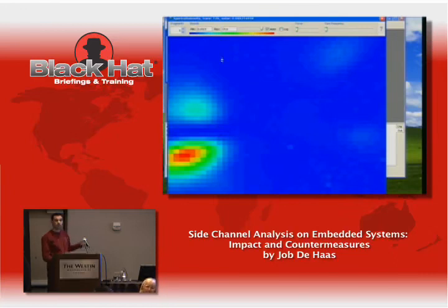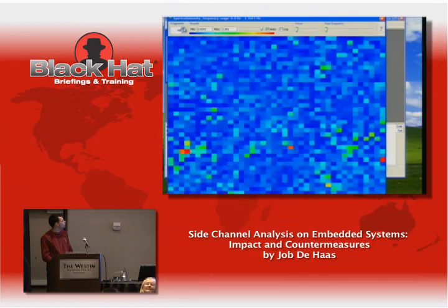And what this does is plot over the XY the intensity of the spectrum. And we can chop that spectrum into pieces. So this was the whole spectrum from, let's say this was 500 megahertz. So from 0 to 500 megahertz, it looks at the intensity of the whole signal. So that's basically the amplitude in this case. But then we can chop it up. So let's say in 256 bits. And then I can start stepping through the spectrum. So now you see this is from 0 to, well, what is it? 1.9 megahertz. So it looks a bit noisy.